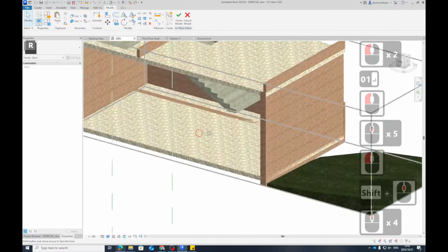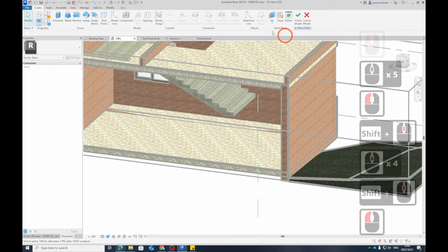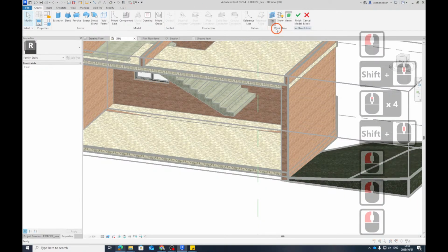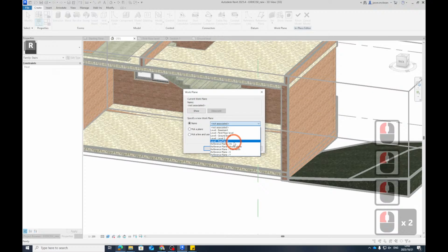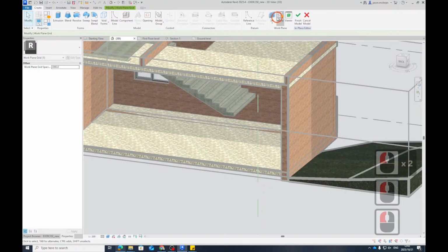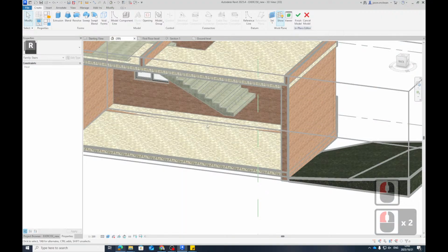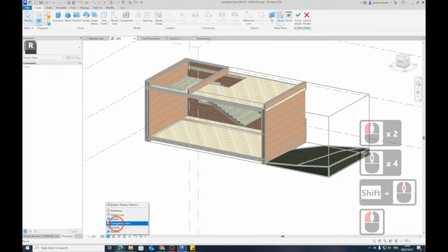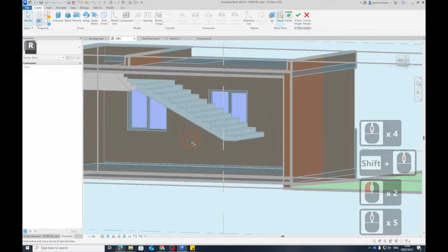So now I'm going to use that as a roof plane, because I'm not in a command, that's why. Pick roof plane. You're going to see 01. And I'm going to go Show. Create and say Show. You see it's on now? Yeah. And if we go to shaded view, you see there's my work plane.